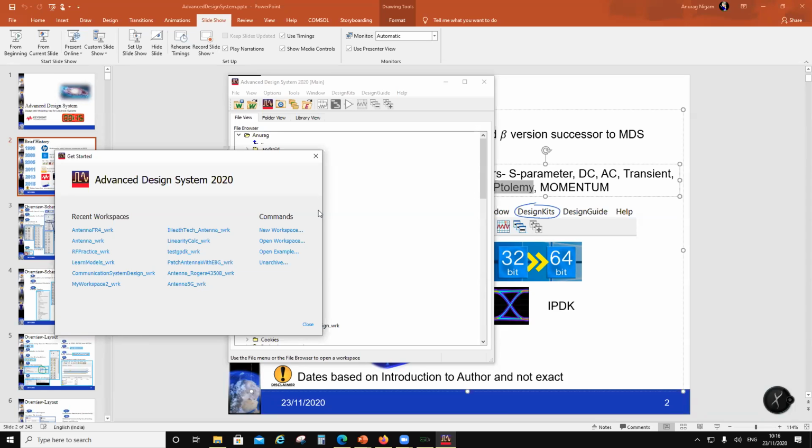It's inside a Volterra series technique. There is a limitation on the number of paths you can simulate in harmonic balance, right? So that's your restriction. So now when you design a transceiver, for example, there are leakage paths, right?